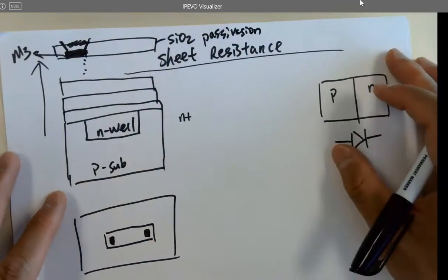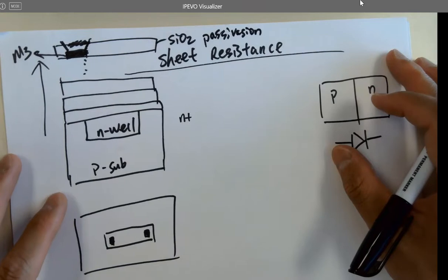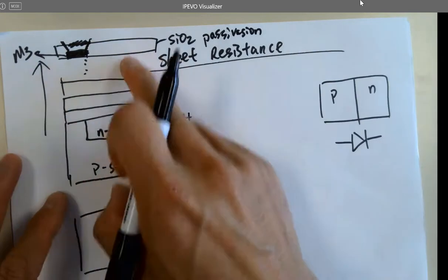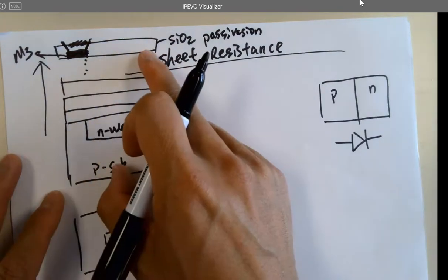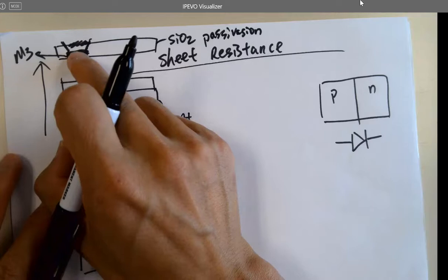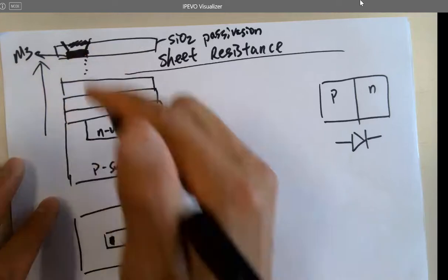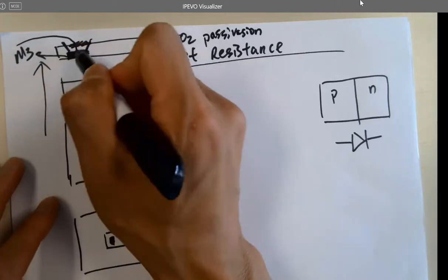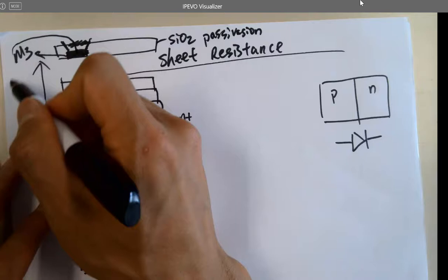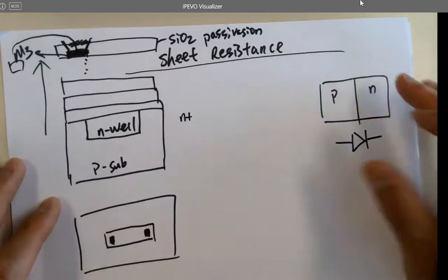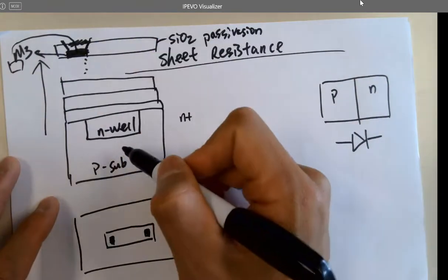Just silicon dioxide, and you can see through. It's transparent like glass, right? And you can see that metal 3 on the top. When you do the wire bonding, you bond the very thin wire to here, and connect it to the pads on the chip to make the connections. That's how you connect all the signals from the transistors.